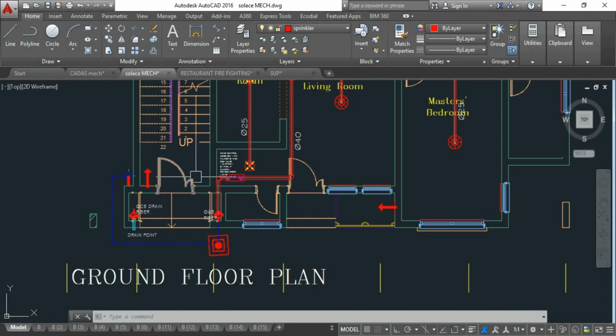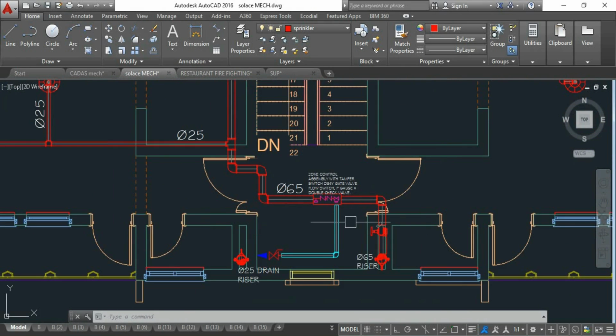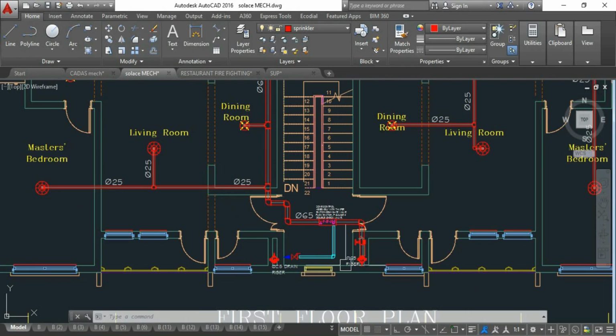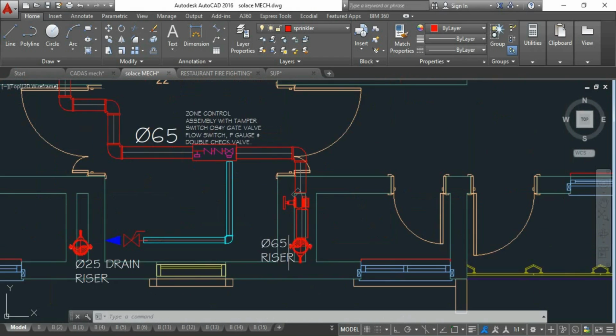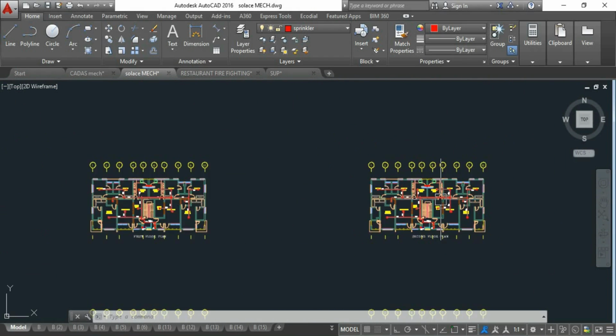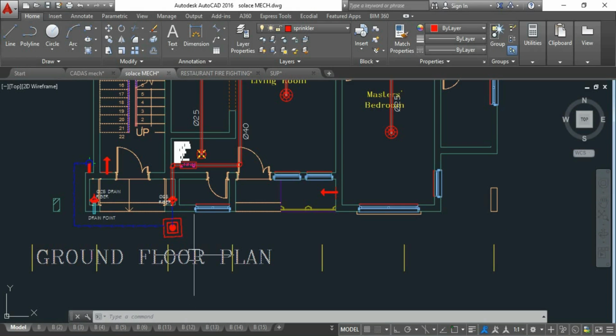But for suspended floors, I mean first floor, second floor, instead of considering the mains, you will rather consider the riser. So for the first floor of this project, here is the riser. So for the ground floor, you consider the main, while for suspended floors, you consider the risers, which is the easiest achievable point to put the riser pipe. So having gotten the riser, you now determine the simplest connection that will reduce the material usage.